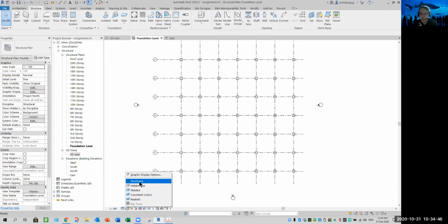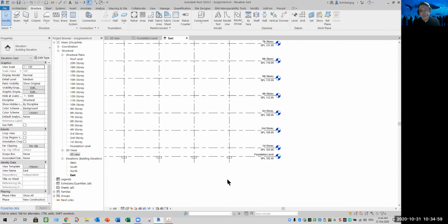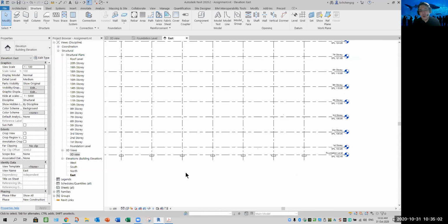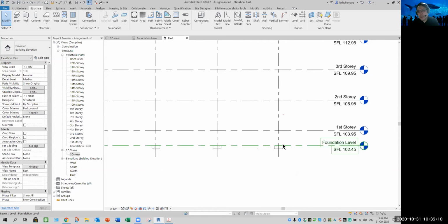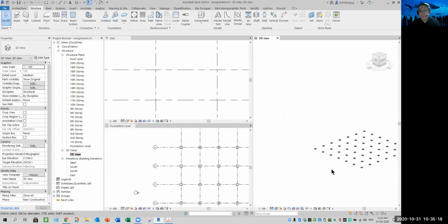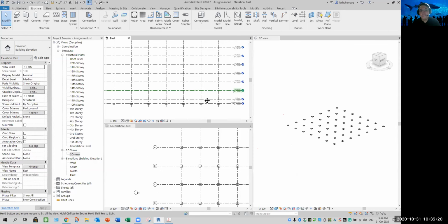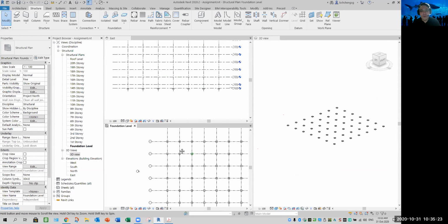Also same for Archi, cannot be wireframe, must be hidden. Unless you are checking view or overlapping. If not, should be hidden. Elevations wise is only to make sure that when you add in your pad or footing, all these are nicely sitting on the correct level. Questions? Anyone? If you don't have, I'll continue.